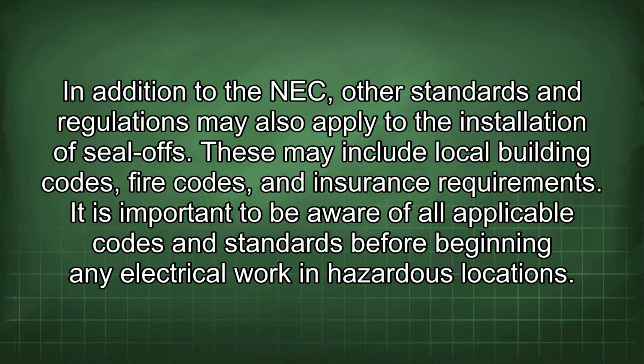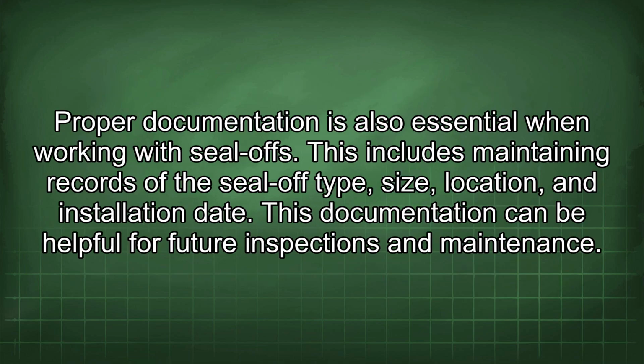In addition to the NEC, other standards and regulations may also apply to the installation of seal-offs. These may include local building codes, fire codes, and insurance requirements. It is important to be aware of all applicable codes and standards before beginning any electrical work in hazardous locations. Proper documentation is also essential when working with seal-offs. This includes maintaining records of the seal-off type, size, location, and installation date. This documentation can be helpful for future inspections and maintenance.